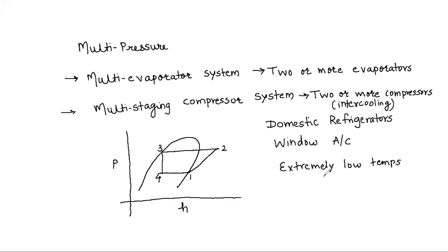Let us say for freezing applications, you would need to take the evaporator to minus 50 degrees centigrade. And for liquefaction, one might need to take it to minus 150 degrees centigrade. These are the typical values. You can remember those. For food freezing, the evaporator temperatures are minus 40, minus 50s like this. And for liquefaction, that is converting gases to liquid, one might encounter lower temperatures.